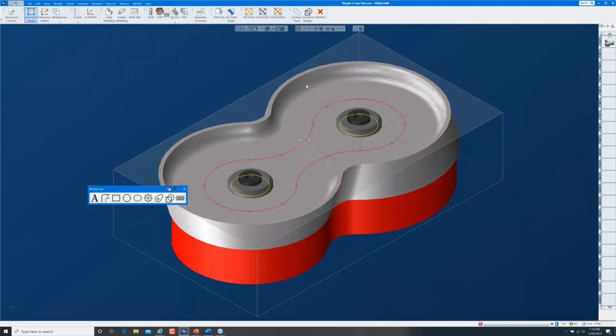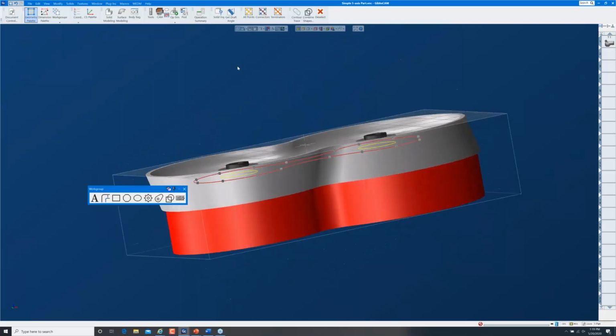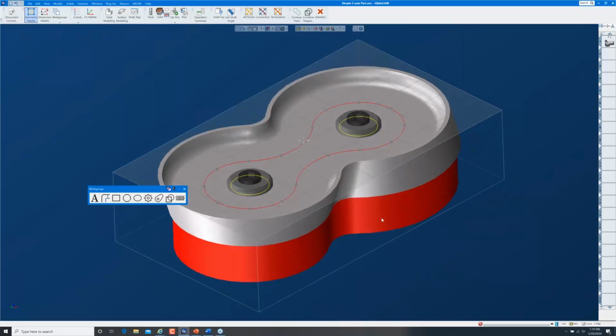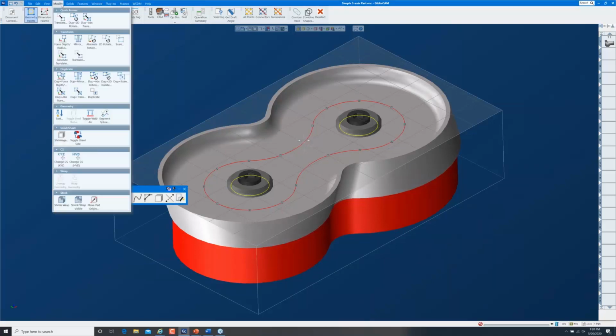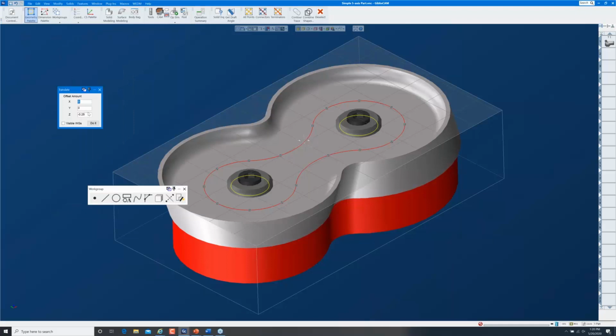All right, so this is a curve that's kind of parallel to, but inside the shape that I'm cutting, smaller than the shape that I'm cutting. However, with it being down on the floor of this pocket, it really doesn't do me any good, because if I project the center line of my tool through this, I'm still gouging, so I need to modify this somewhat. So I'm going to translate this up, and I'm going to go, say, a 1/2 inch a couple of times, and maybe one more time. So that's 1.5 inches above the floor of that pocket.